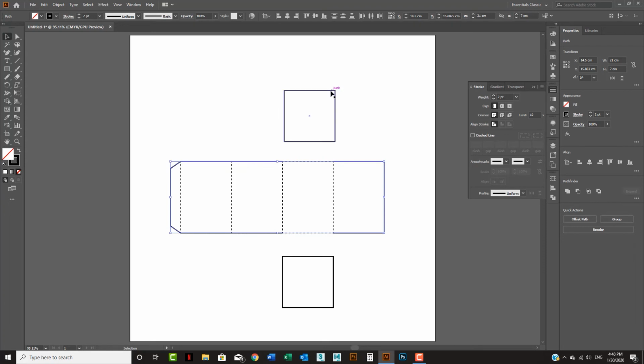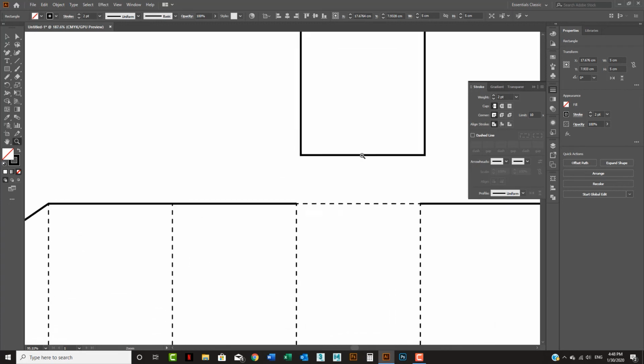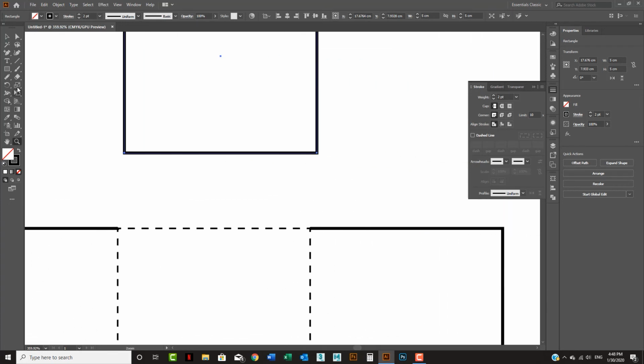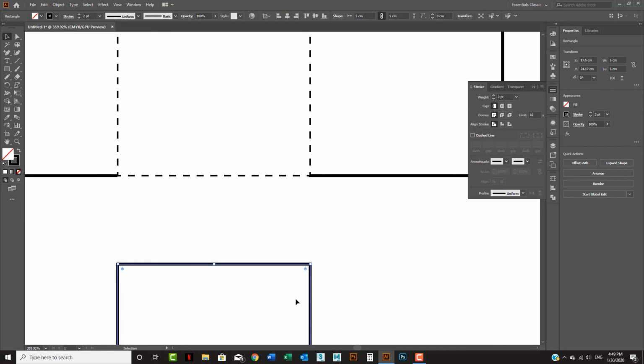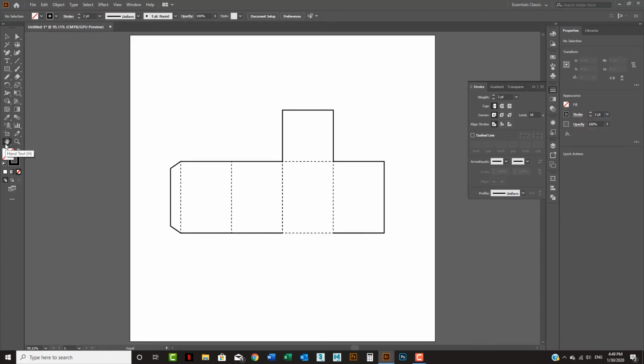Same here, it's happening in here too. It's an easy thing again. So I'm going to focus in here. Again, I'm going to the path eraser tool. Easily I'm going to click and drag. Don't worry about how accurate you are; Adobe Illustrator is a smart guy and understands what exactly you need. Here we go. So I have this one here. I'm going to delete that one. Double click on the hand tool to see everything. And I'm going to select this one, but I need exactly the symmetrical shape, or the mirror part of this one in here too. So I'm going to use the reflect tool.